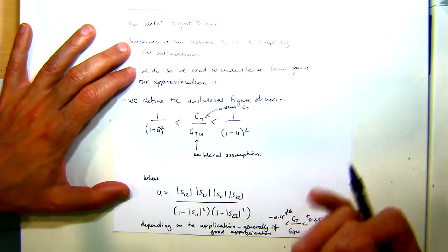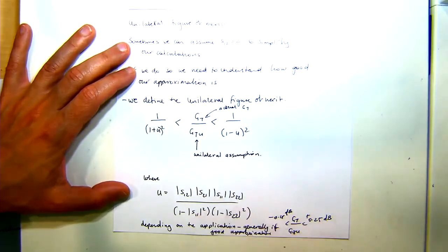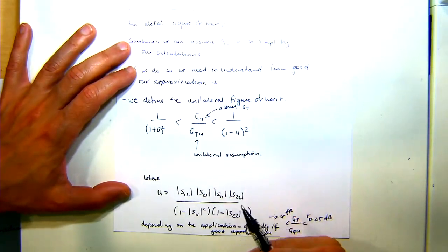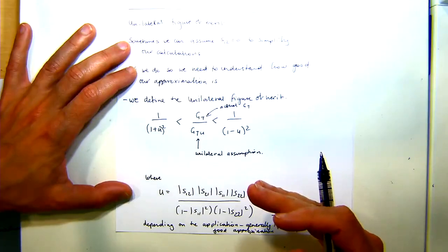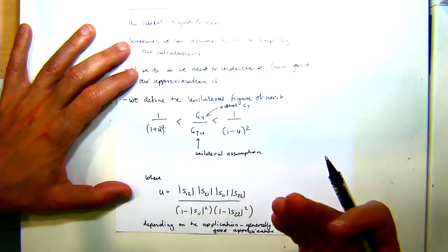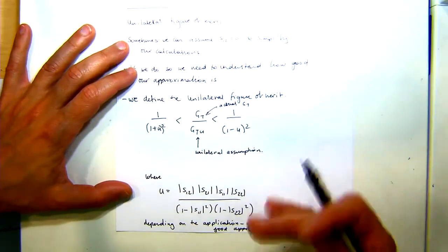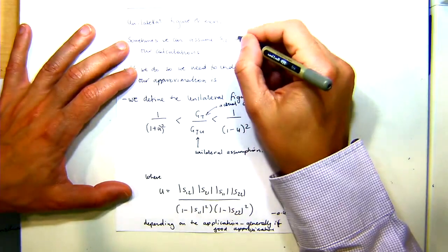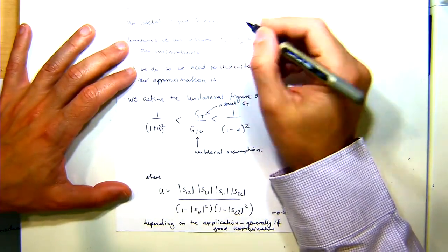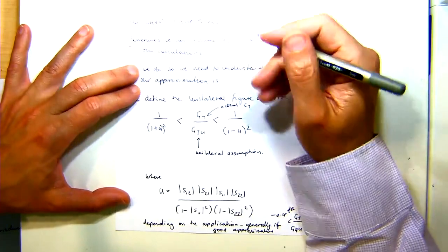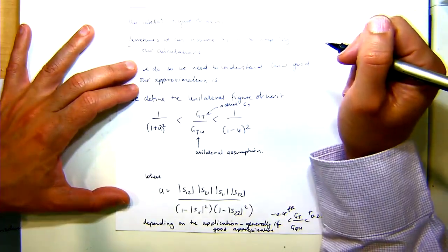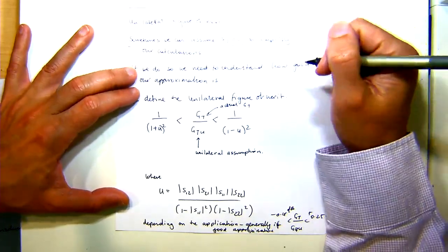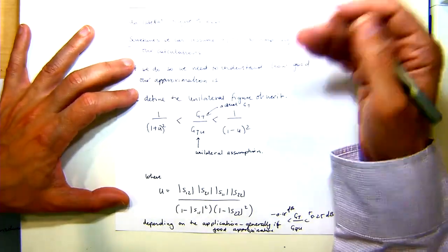But in order to draw the gain circles and do all this mathematics, we've assumed that S12 was equal to 0, right? That's our assumption. So now, either it is equal to 0, or we're saying let's assume S12 is equal